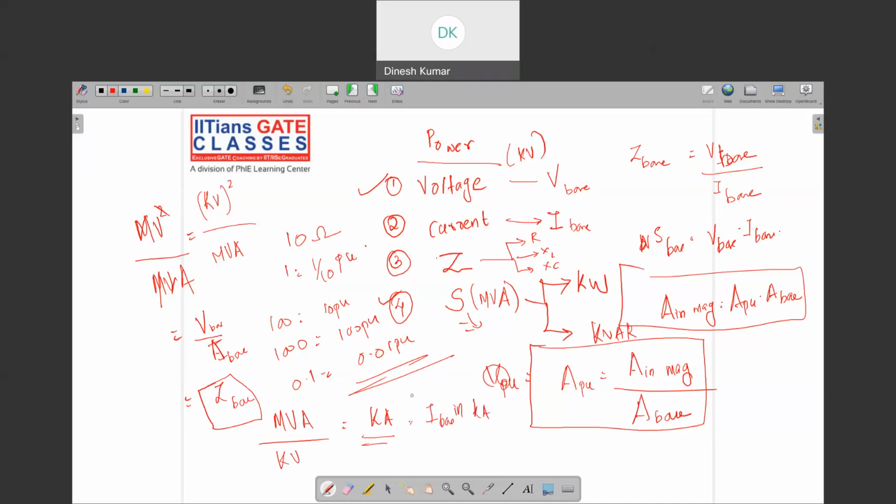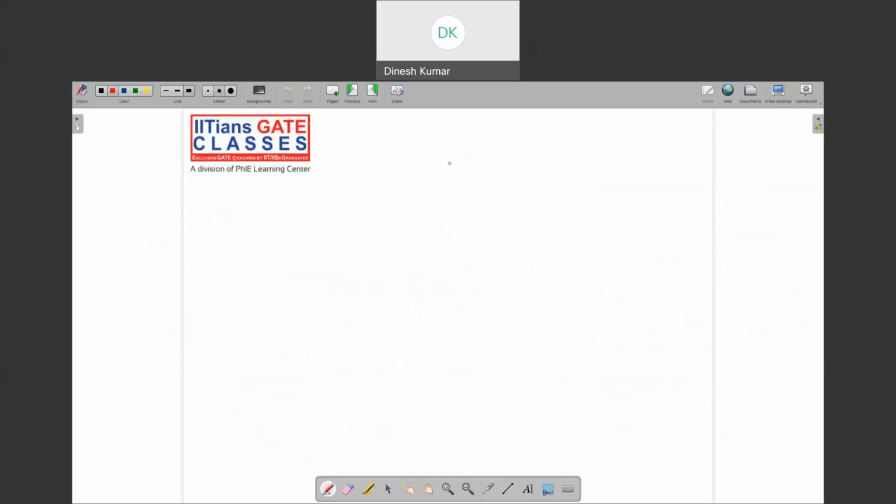So we get everything in kiloampere, and our base is basically 1000 times the I base in ampere. This much kiloampere will be our base. So if we take any two bases, we can find the other two from these. We cannot take four different bases arbitrarily. Even if you take four numbers, they should satisfy these two equations. What are the equations it should satisfy?